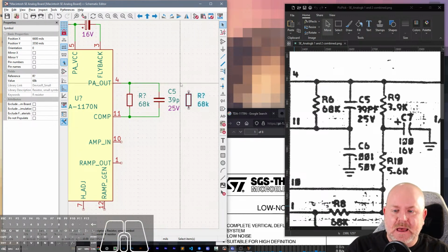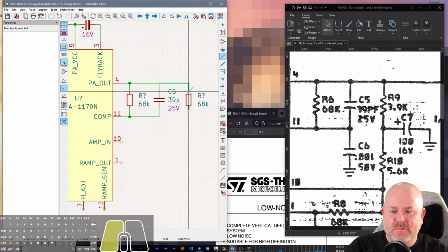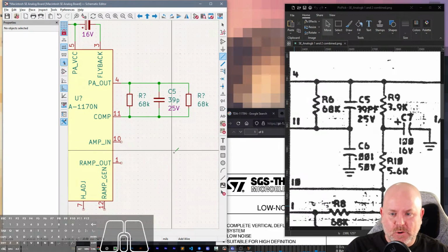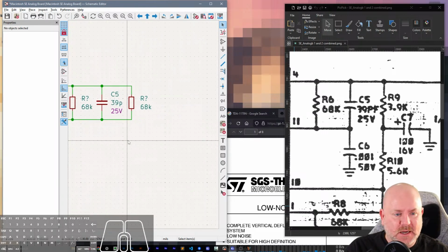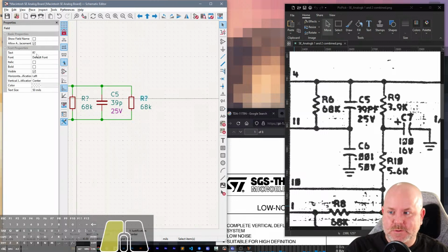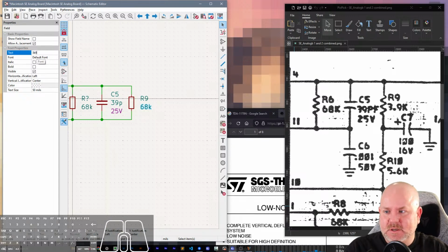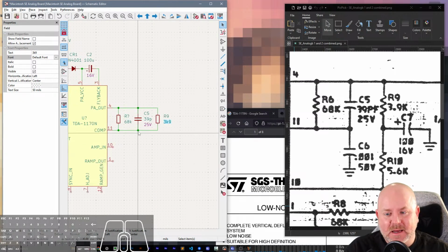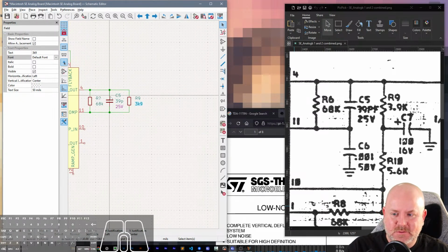I have the small variants of resistors and capacitors with 0805 footprints already assigned to them, since that's the most common that I had been using. I'm actually transitioning to 0603, and as I get to a point where I'm going to start using assembly services, I'm going to get down to 0402s, because I can rework an 0402. I can hand solder an 0402. I just don't like to.